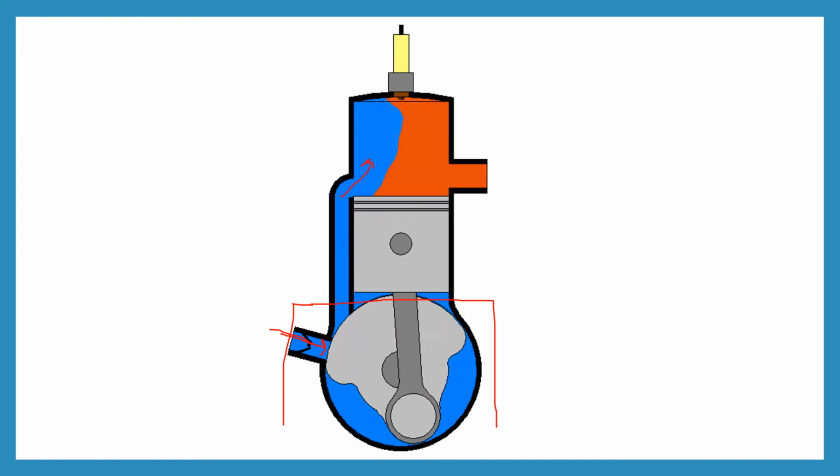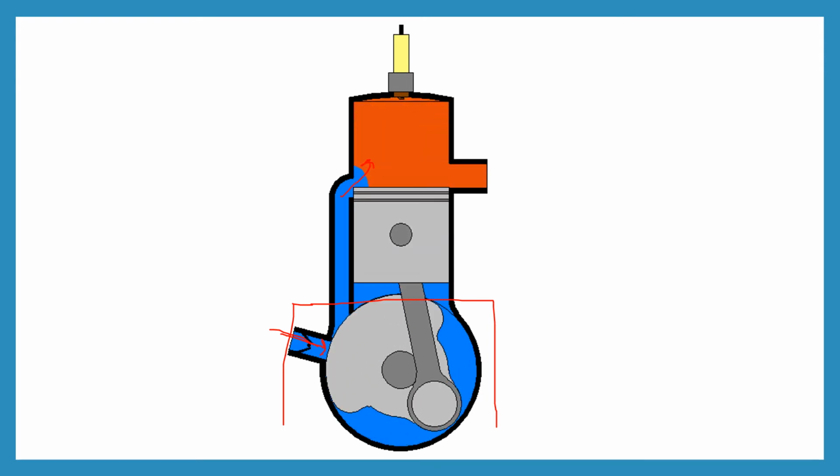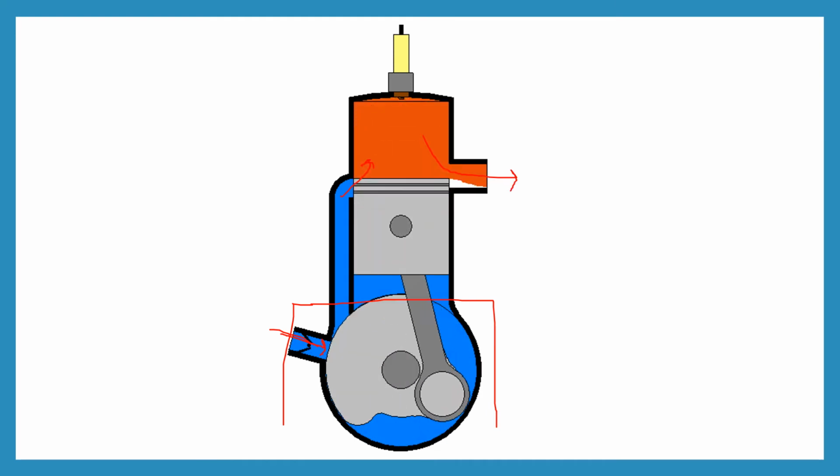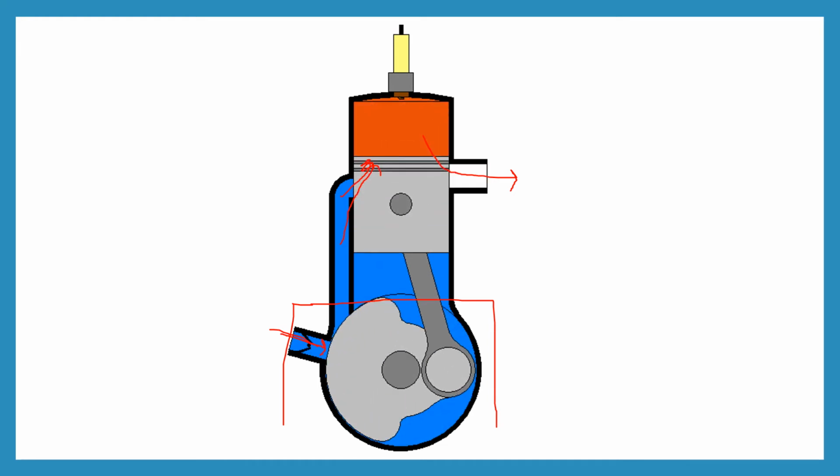The piston moves from TDC to the BDC, and it first opens the exhaust port, and through the opening of the exhaust port, the exhaust gas or the products of combustion are emitted, and at that time intake charge is again introduced in the combustion chamber. So in this way, in every revolution of the crankshaft, the power is produced.